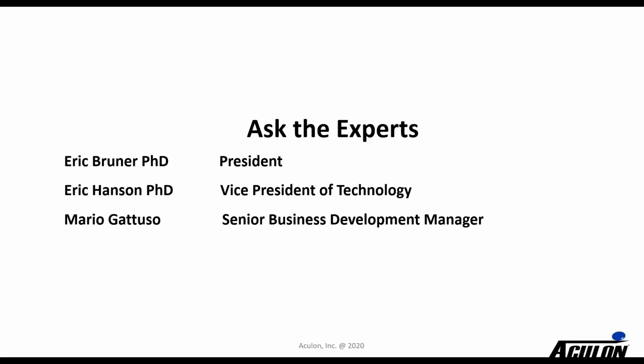Okay, I have a question for Eric Bruner. Have you attempted inkjet printing patterns? Absolutely. A lot of our nanoproof coatings are actually designed for inkjet or jetting type applications. A lot of times it's a question of what type of nozzle and what the viscosity need is. So there may be some tuning necessary depending on the actual equipment. But we've done quite a bit of that, especially around patterning circuit boards with repellency treatments.